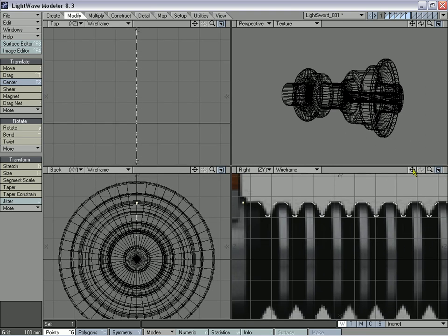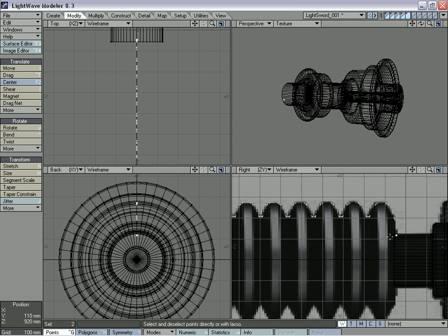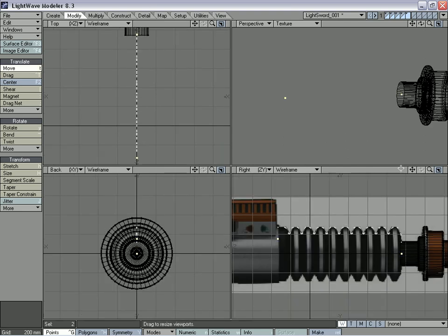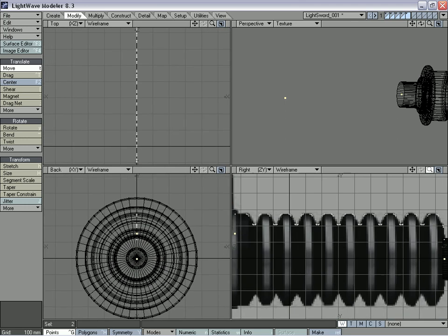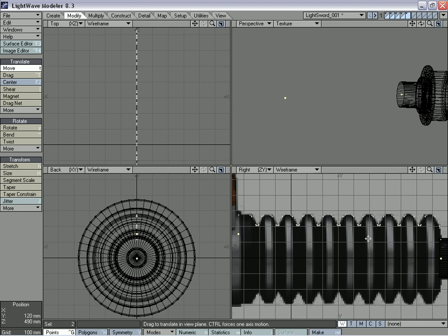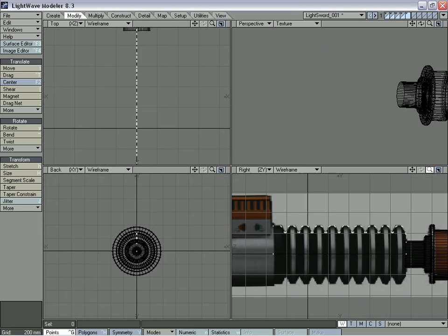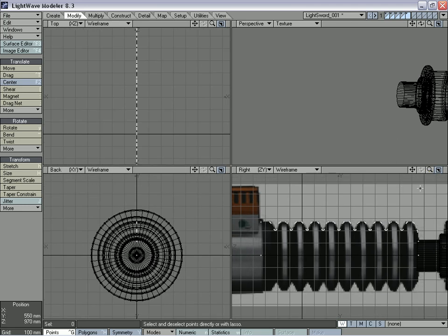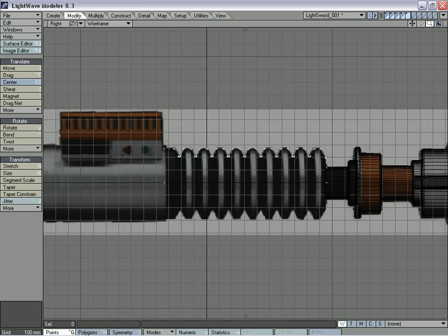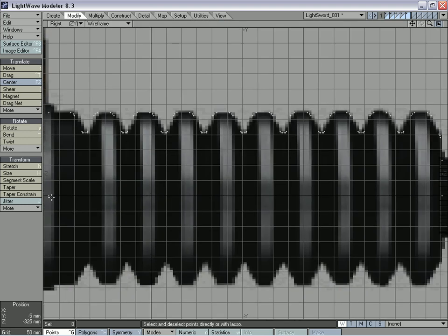So we'll take the endpoints now, and we're going to copy and paste and move them down a little, so they frame that, using Shift A to frame selected within the viewport, and we're going to set the value 0 on the Y. And now we're ready to create our polygon. And for this we're going to need to be zoomed in a little bit more and want to be able to see what's going on. So the 0 key on the number pad to bring it up full view and go around and just select all of our points.